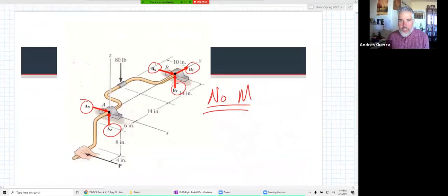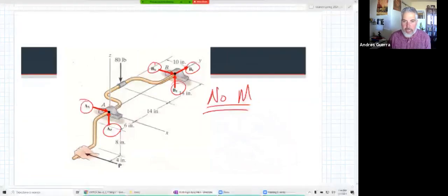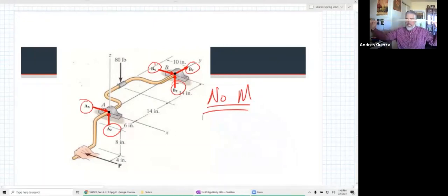Okay, so those moments go away because we're perfectly rigid. And remember, perfectly rigid means that my yardstick does not do this. Perfectly rigid means that no matter how hard I push, it always keeps the same shape. But if I don't have another support reaction, I need to carry a moment right here. As soon as I get another support reaction, I no longer need to resist moment, as long as this is perfectly rigid here.